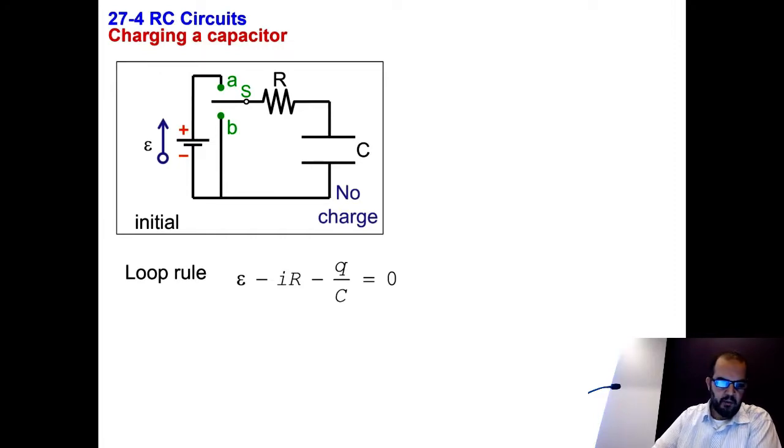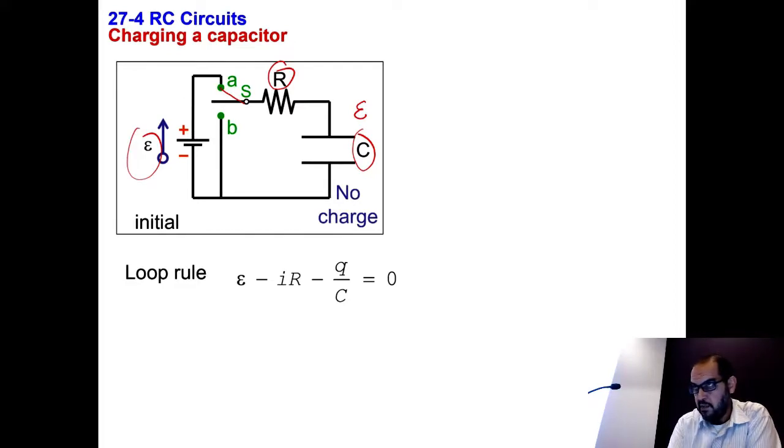Usually, we have a battery, and let's assume this switch here is not connected to any place, and we have a capacitor C and the resistance R. If I want to charge this capacitor, I can switch the switch to this position, and it will be charged. Remember, when we studied capacitances, we said when you connect it, the potential across the capacitor will match the potential here. So eventually the potential across the capacitor will be equal to the EMF.